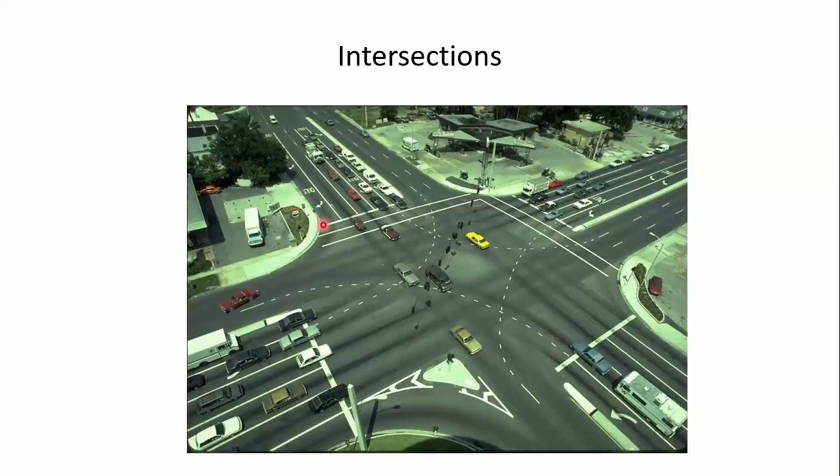In fact, interestingly, notice they just marked these two walks here, a channelized slip turn lane here. They don't really want to encourage pedestrians crossing here. Directly related to the convenience store combination. And notice there's driveways here. And so that's another conflict for pedestrians even trying to reach the street corner.